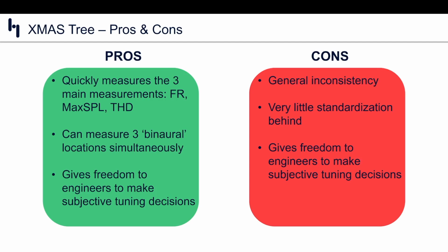Impulse distortion, buzz, squeak, and rattle. The idea is to uncover artifacts that the human ear would sense, which wouldn't necessarily be picked up by the frequency response measurement. The goal is to focus on a full system measurement and on the most basic attributes that are widely used in the industry. This could allow for easy vehicle comparisons.